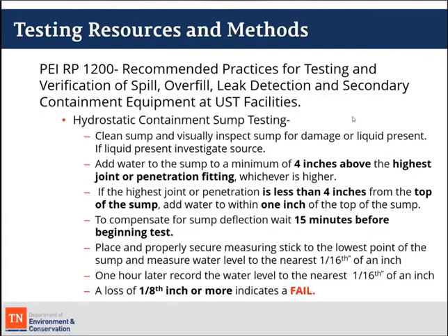You also want to do a visual inspection of the sump, all of the boots within the sump, for visual damage. Obviously, if you've got a big tear or a crack in the bottom of your sump or sidewall of your sump, you can fail that sump just by a visual inspection without even filling it full of water. If you've got a big tear in a boot, that sump's probably not going to pass. So you would want to address the visual damage before performing your hydrostatic test.